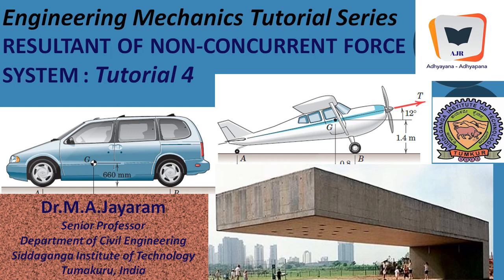The gist of the matter is, while finding unknowns in a non-concurrent force system that is in equilibrium, we have to press three equations into service. Number 1, sigma Fx equal to 0. Number 2, sigma Fy equal to 0. Number 3, sigma M equal to 0. Algebraic sum of moments with respect to some point should be equal to 0. Algebraic sum of horizontal forces should be equal to 0. Algebraic sum of vertical forces must be equal to 0.